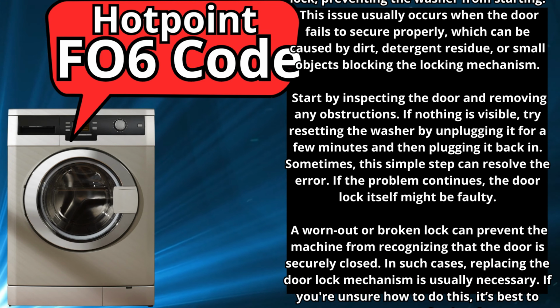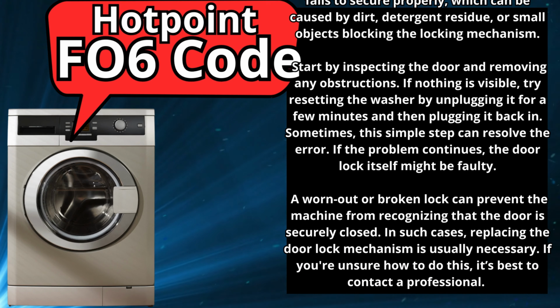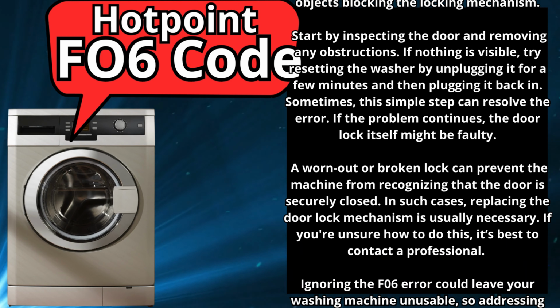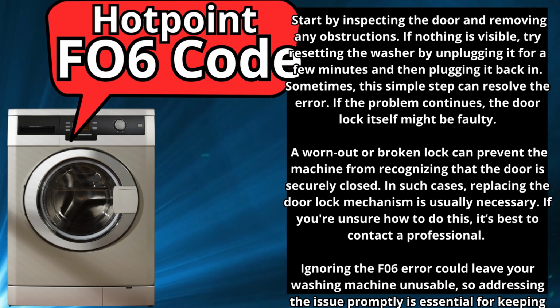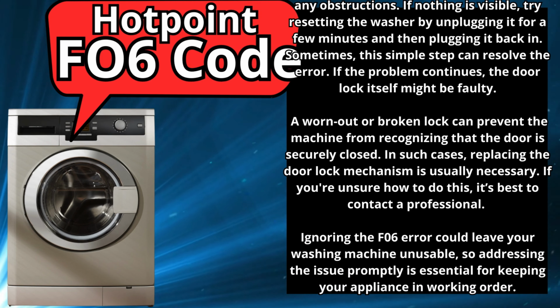If the problem continues, the door lock itself might be faulty. A worn out or broken lock can prevent the machine from recognizing that the door is securely closed. In such cases, replacing the door lock mechanism is usually necessary. If you're unsure how to do this, it's best to contact a professional.